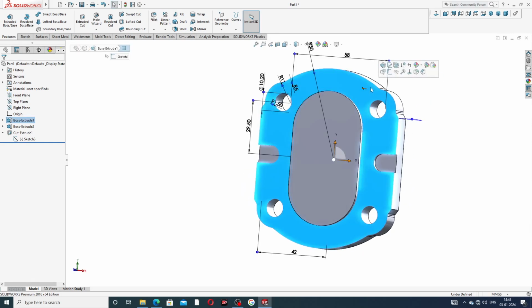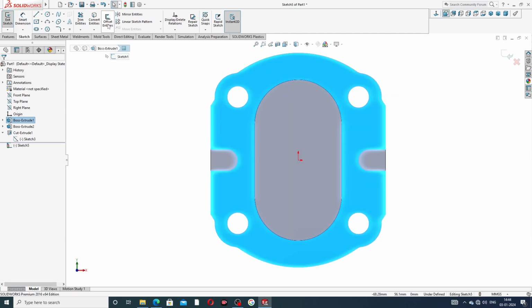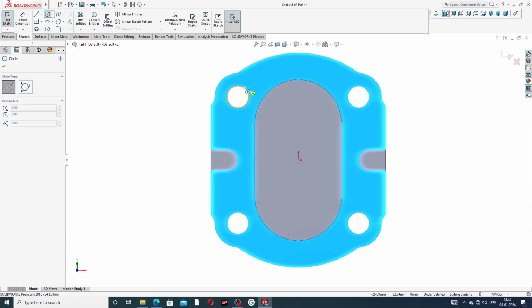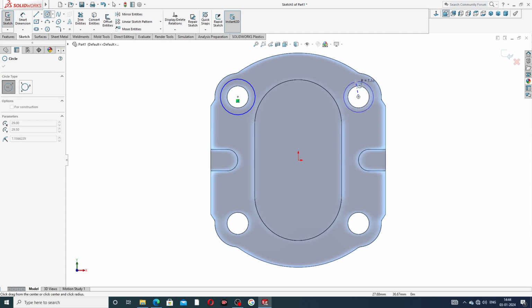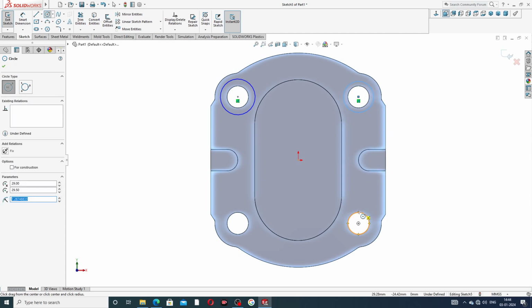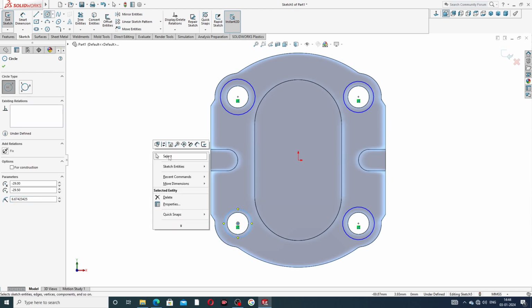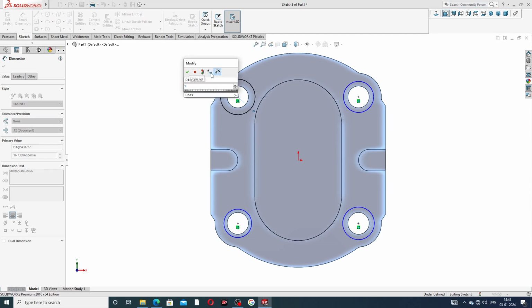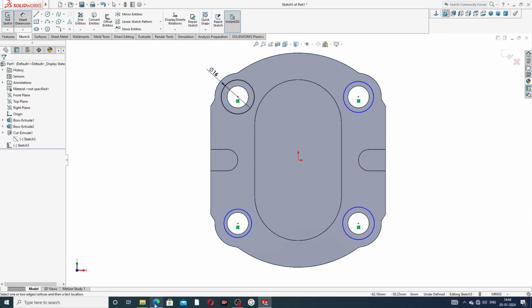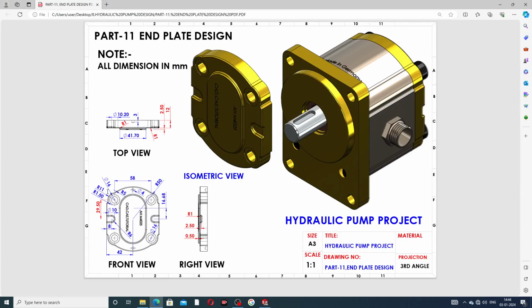And next, this face, Sketch Normal, drawing a circle like this, and one by one at all center points, draw a big circle here, and this dimension is 16 millimeter. This 16 millimeter circle is cut out, with a thickness of 0.5 millimeter.